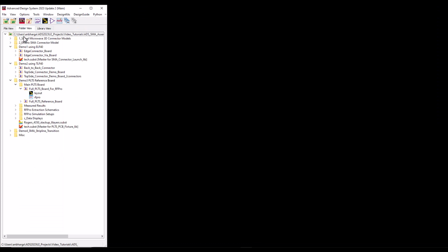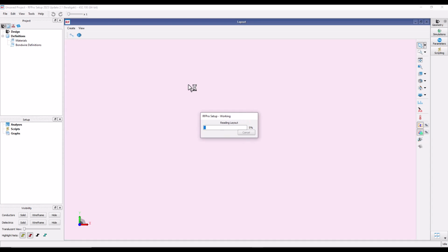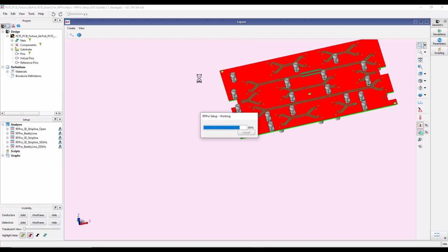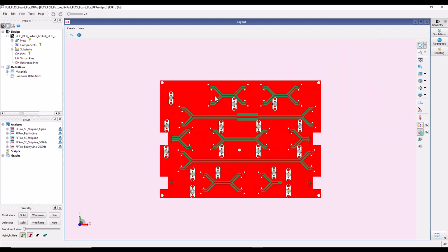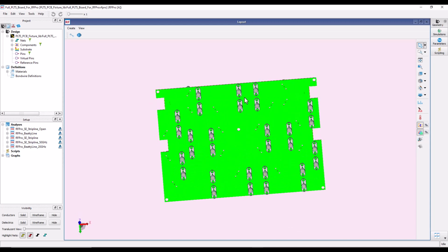All right, finally, I'll show you one last, pretty complex assembly where you can utilize the power of both RF Pro as well as the flexibility which is given to you by modeling your own component in EM Pro. So here we do have almost 40 plus SMA connectors, which you will see just now. It's one of the Keysight reference test boards which we use along with our instruments. In here you can see the 6-layer board with plenty of SMA connectors at the top, and then you have plenty of SMA connectors at the bottom.